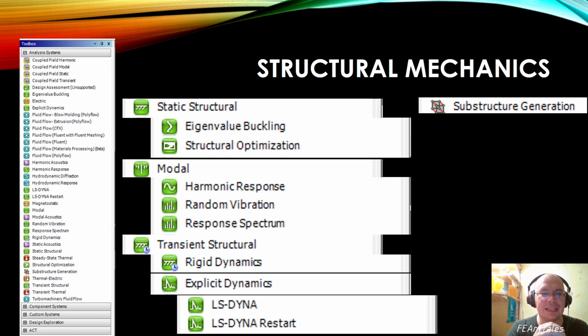Some people say that it's a resonance frequency and resonance form, but it's not fully correct to use this term. It's modal, the natural frequencies of this construction, not resonance, because whether it will be resonance or not, we can know with those additional types of analysis.